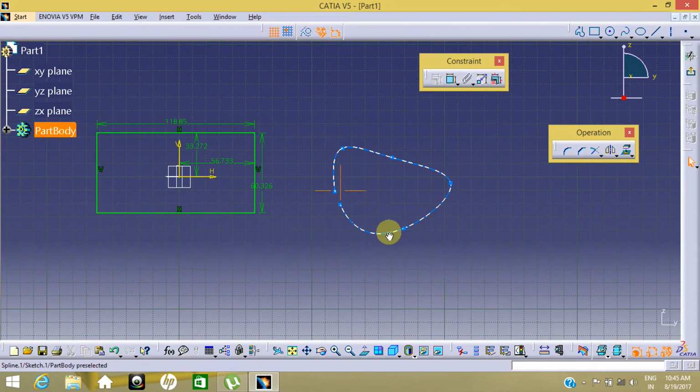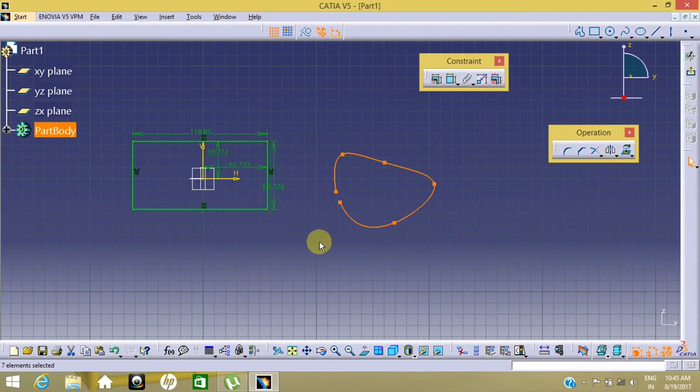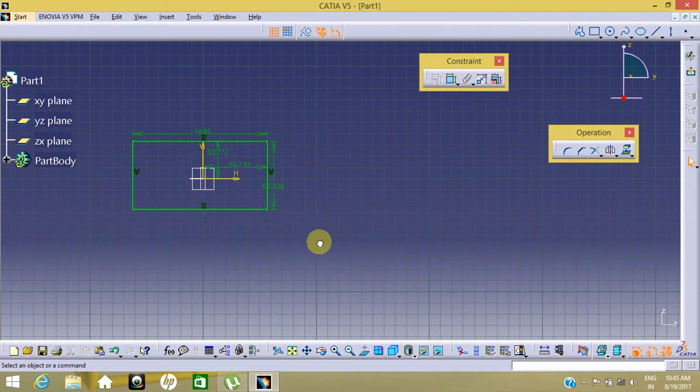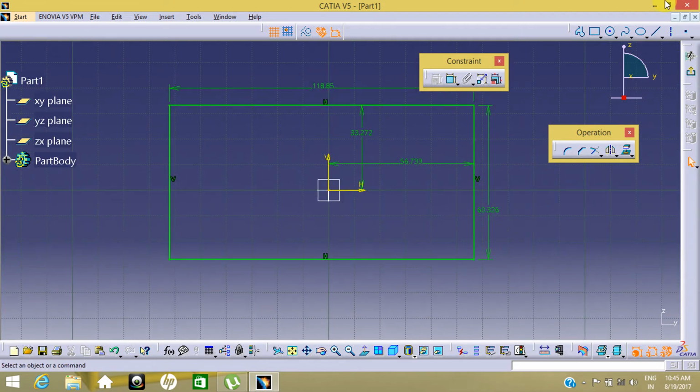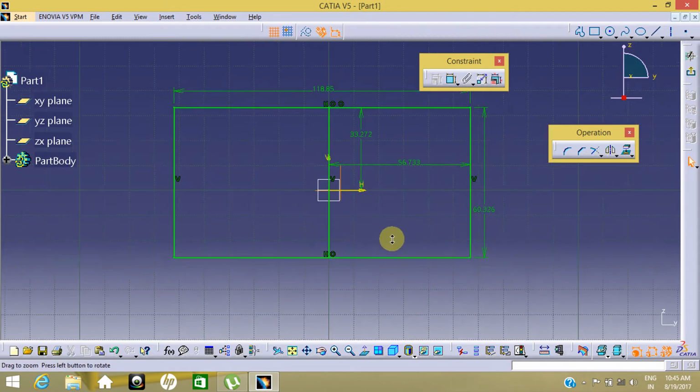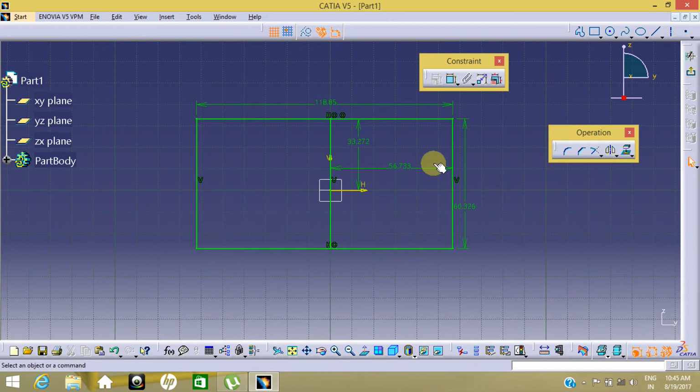What will you see here? Is this sketch really closed? Let's see. If I start moving from here, then I start moving here. Now we have an intersection point between two paths. Our sketch should not contain an intersection.